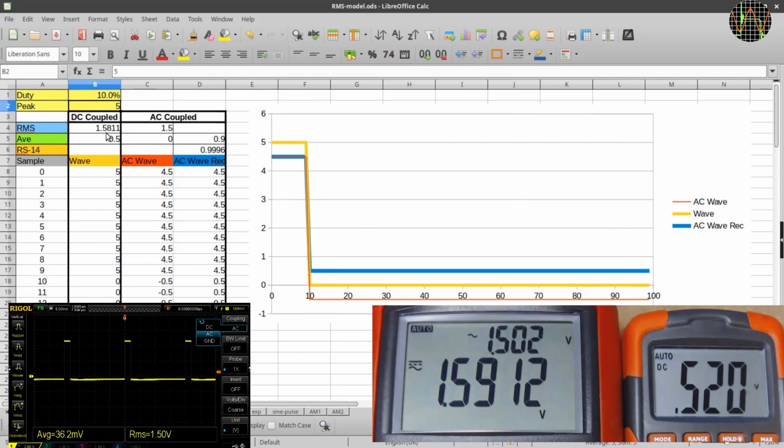The pulse or square wave is a waveform where we can potentially rescue the averaging meter by applying a correction factor. We have already discussed this 1.111 factor in the case of 50% duty cycle. How would that factor look like for other duty cycles?